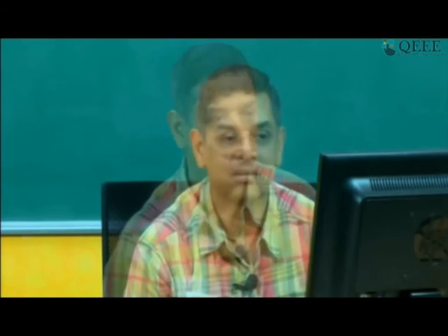Now again we'll keep it in this slideshow mode and open it for questions. Interaction with PECUT SK Verma. Good afternoon. First of all, is there any guidance regarding the block shear patterns to be identified? The code gives you only that rectangular pattern. So the block shear rectangle, the perimeter should encompass all the bolts that are there in the connection.